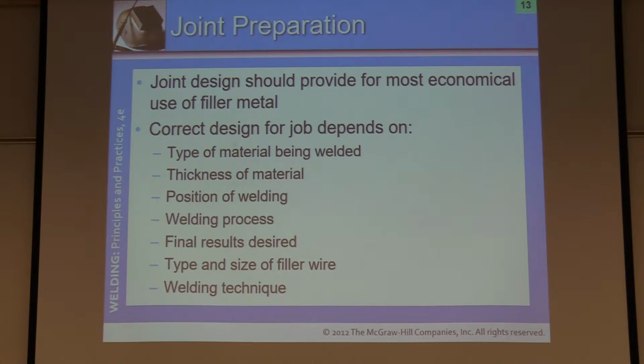The joint design should provide for the most economical use of filler metal. Also make sure that you're getting complete fusion within your joint preparation and joint design, okay? Correct design for the job depends on the type of material, thickness of material, position of welding, welding process, results, and so forth. Technique, type and size of filler metal, absolutely.